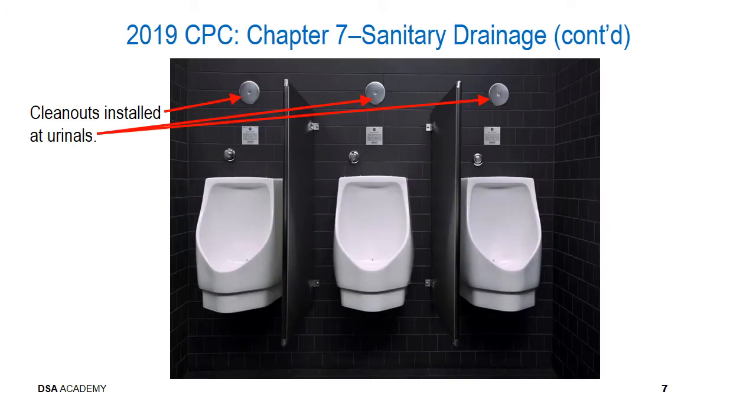As a follow-up from the last slide, here's an image that basically depicts what you would expect to see from now on with new construction for urinals, where you can see where the arrows are showing the cleanout covers above each of the urinals.